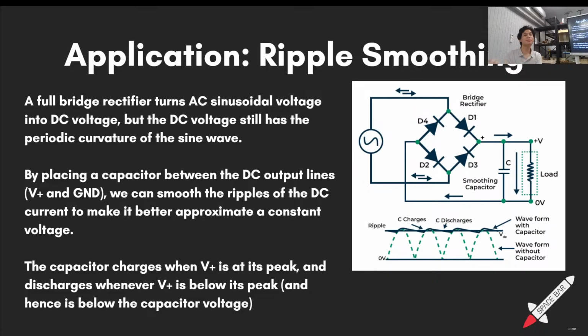There are other problems with having too big of a capacitor, because when you plug your circuit in, all the capacitors on your circuit are going to charge at the same time. So you have this huge inrush current. Usually too big is not that much of a problem, it's fine, bigger is better. Just don't be ridiculous. No 1 farad capacitors.